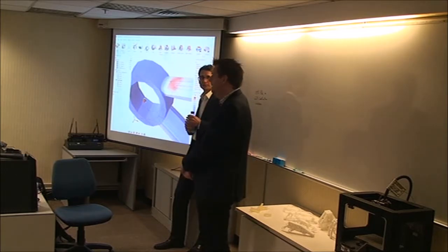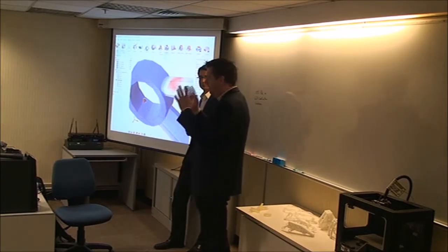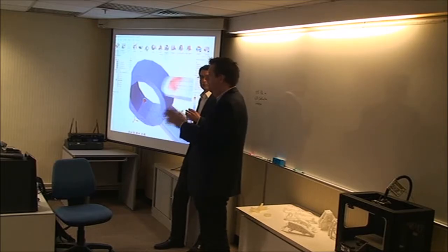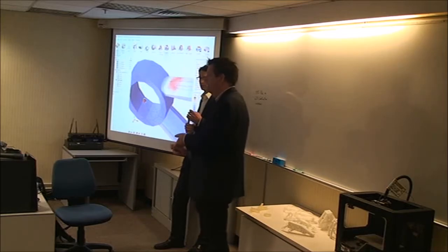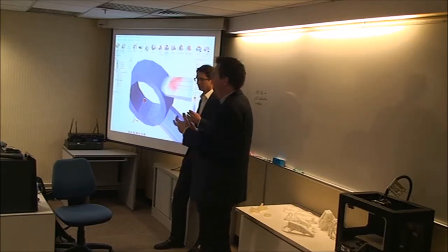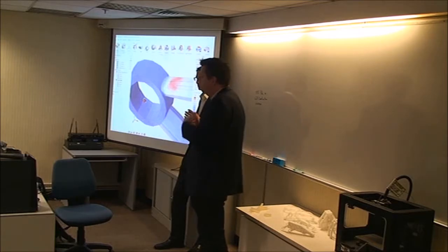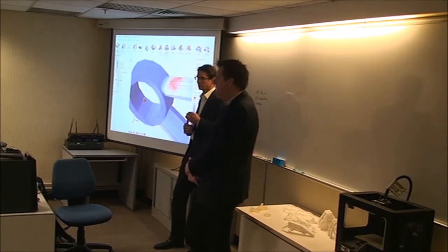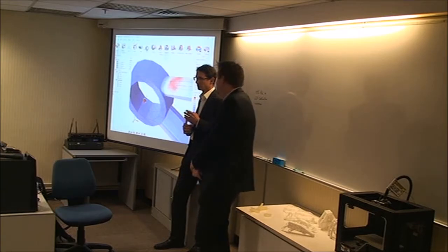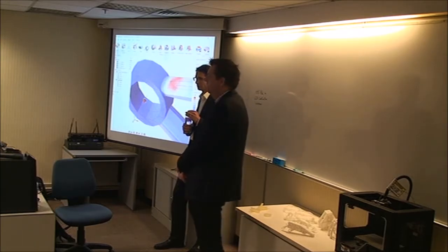You find that a lot of the large automotive companies, like Ford, have their own very clearly defined processes for how you build these models. They define what your element size should be, and how you should model your connections and your welds. So that's all very clear, and they've spent years verifying that. And we try, and LT has done that as well. That's what we try to put into Inspire: all those rules that we have for building a good quality model.